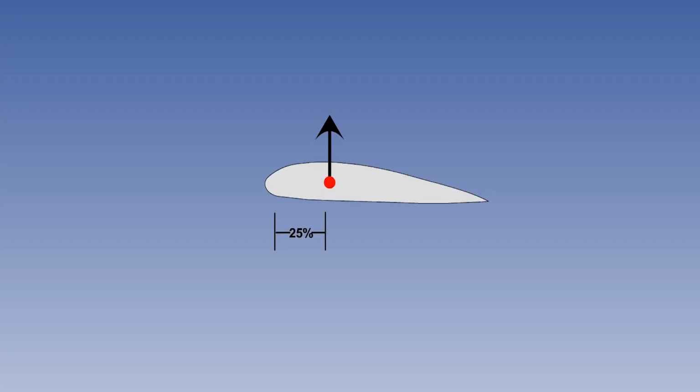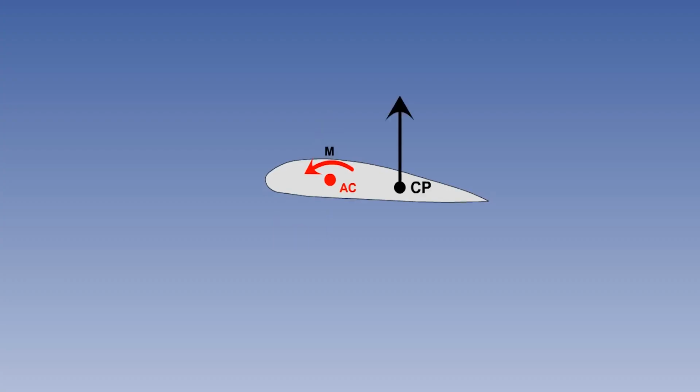The AC is an aerodynamic reference point, which is used for examination of the theory of incompressible airflow, and is most directly applicable to longitudinal stability, as you will see later in the syllabus. There is a nose-down pitching moment about the AC, which is a product of the lift force at the CP and the arm between the CP and the AC.